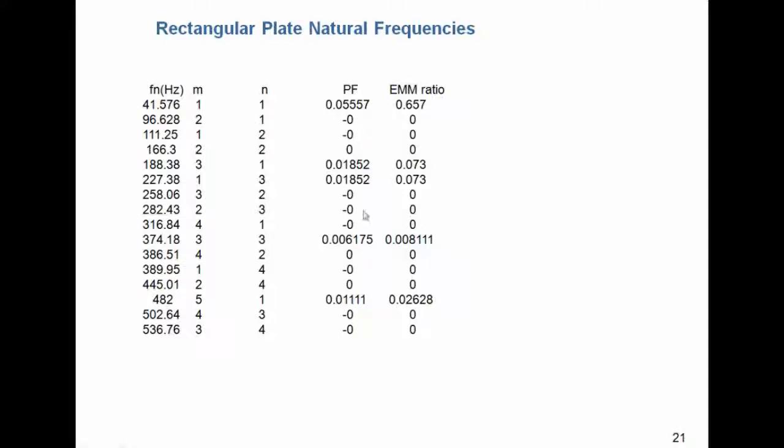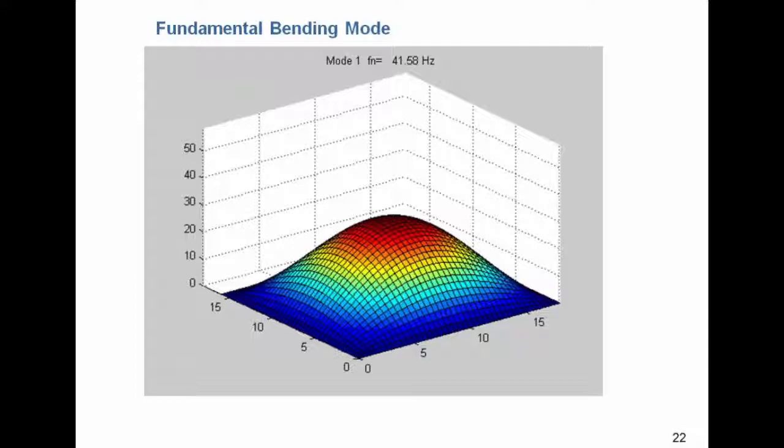If we took enough modes and we took a summation of these EMM values, eventually the summation would converge to 1. And here was our fundamental mode, which looks like a turtle shell, where most of our stress and fatigue damage is due to the response of this first mode.